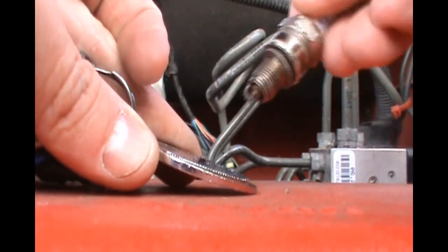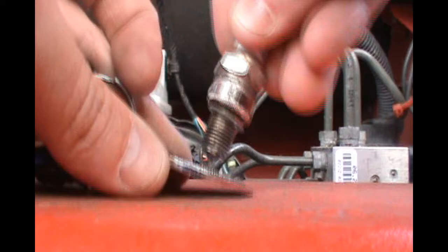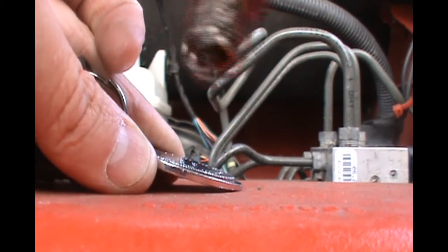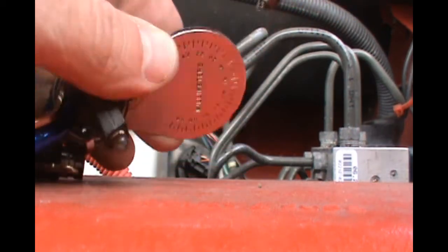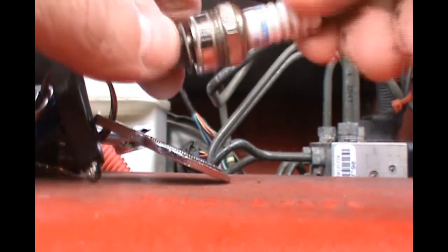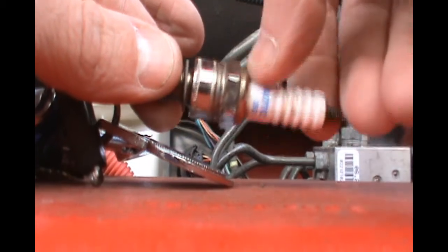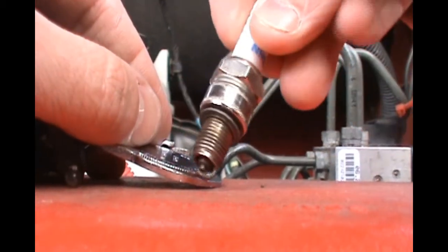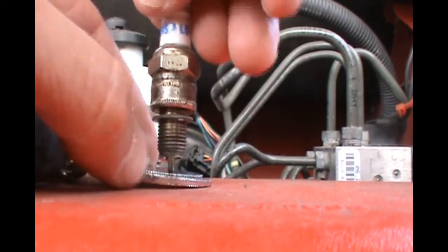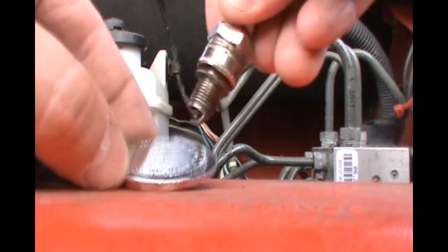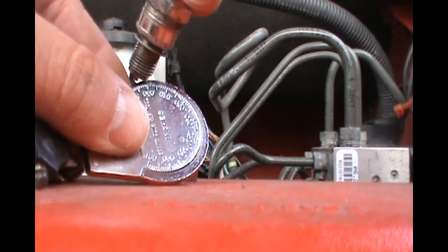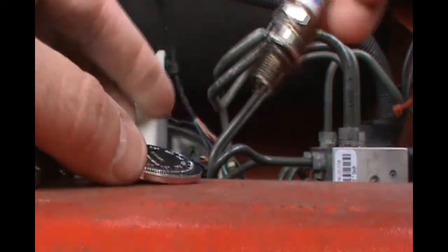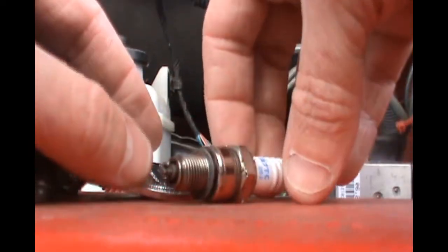Now again, I said gently. Well, how hard is gently? Because I can tap this thing until it's flat and crush this in all the way. So you can see it getting smaller. But the last thing you want to do is drop a spark plug. If you damage this insulator or if you damage the electrode, the spark plug is no good. So don't drop it, don't beat on it. Pressure, gentle pressure, don't lose your grip, and then check your gap. Pretty simple, right? Now you have to do this 8 times for this truck, only 1 time for the buggy.